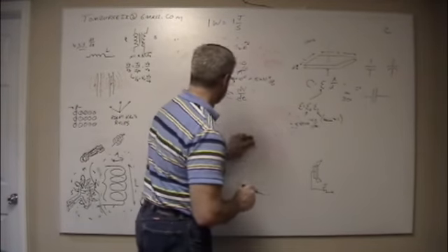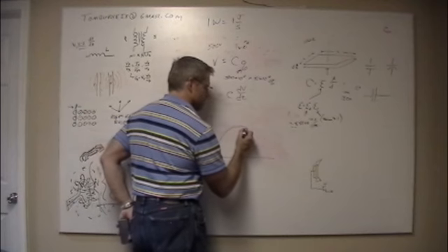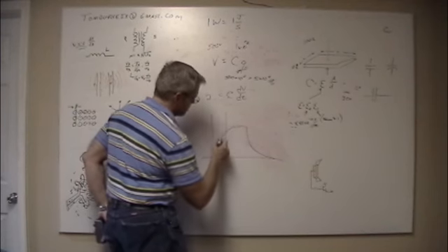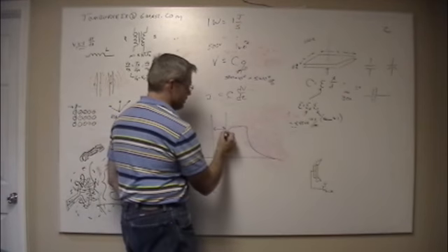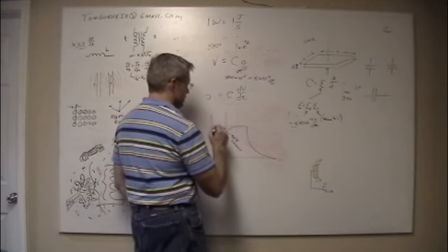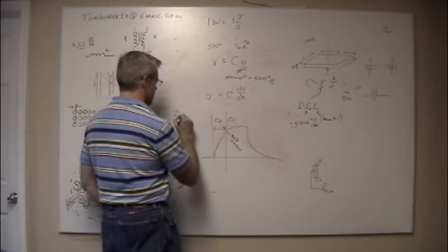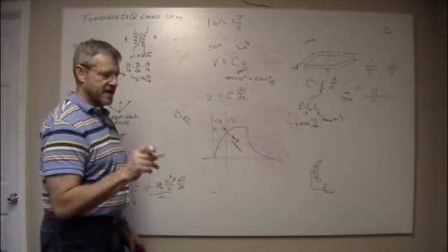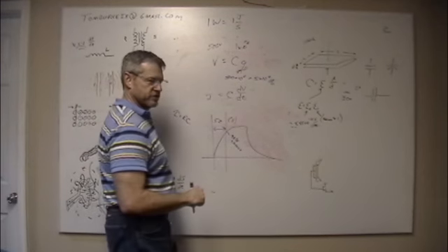What happens is the discharge rate. When you charge it up, it charges fast and then it slows off. It's an exponential. And then when you discharge it, it discharges fast and then it levels off. And this time here, I'm going to call tau. I've done the math behind this. The point to where you get to about 98% charge is 5 tau, which is in seconds, and tau is equal to RC. So tau is your time constant, RC is your time constant. 5 tau, or 5 RC, is the time in seconds it takes to get to 98% charge